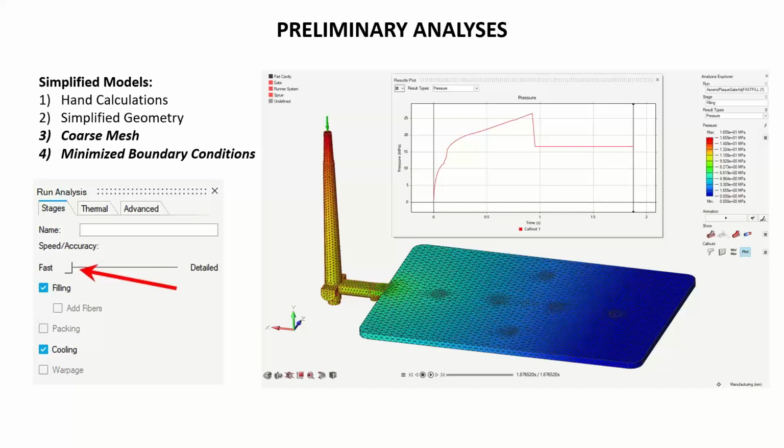And so I can certainly identify things like the pressure, when I distinguish my melt temperature, my mold temperature, and my fill time. When I'm looking at those 3 things to develop my process window, this is a great way to do it because it runs a lot faster. I can look at that pressure to fill.